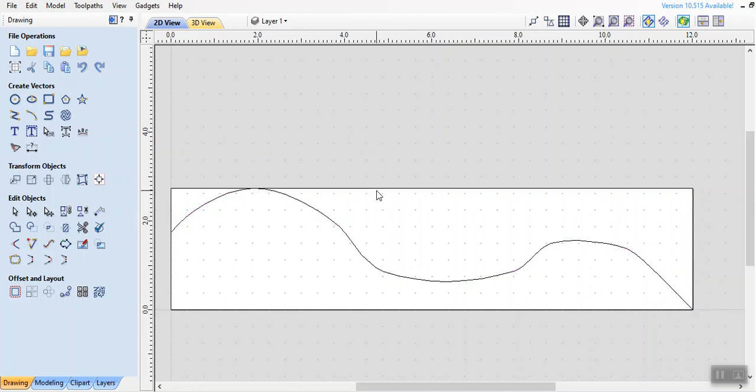Good. And I'm going to do the same thing, but remember I copied this before with the Control C. Now I'm going to type Control V to insert what I copied earlier. You see the old line, but actually there is a new line that came here. I'm going to press the shift button and select the two lines at the bottom. Now I'm going to join these two also using the join close vectors by moving endpoints to common point button. Click on it.